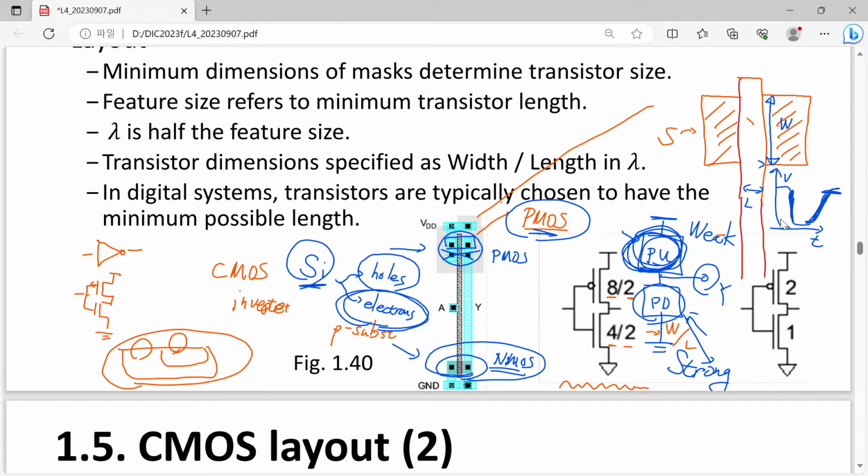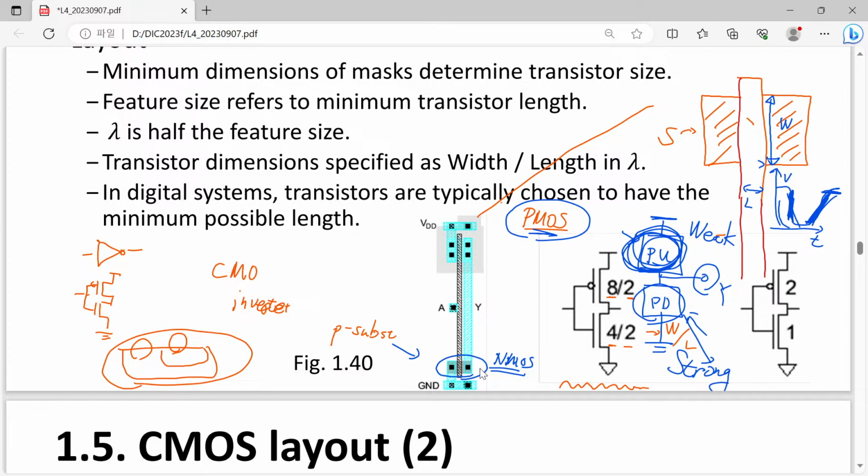You may say that, okay, even though we have a slow reaction, but still here we have a fast reaction, so it's good. No, it's not. The best way is just a balanced one. I would rather have just a balanced one instead of this highly unbalanced one. So please note that. That's the reason why usually we introduce different widths for our PMOSFET and NMOSFET to balance the strength of our pull up and pull down circuitry.